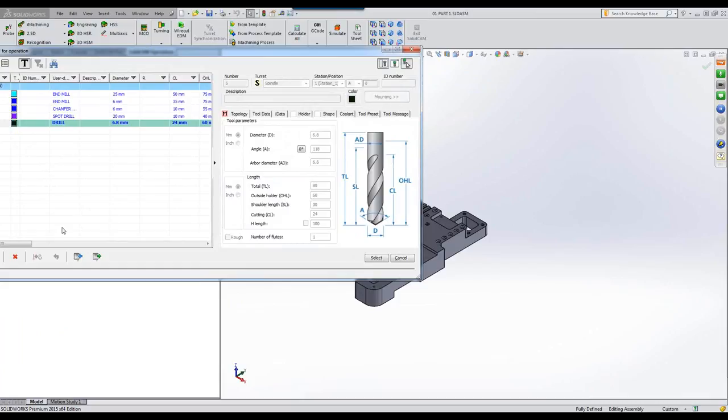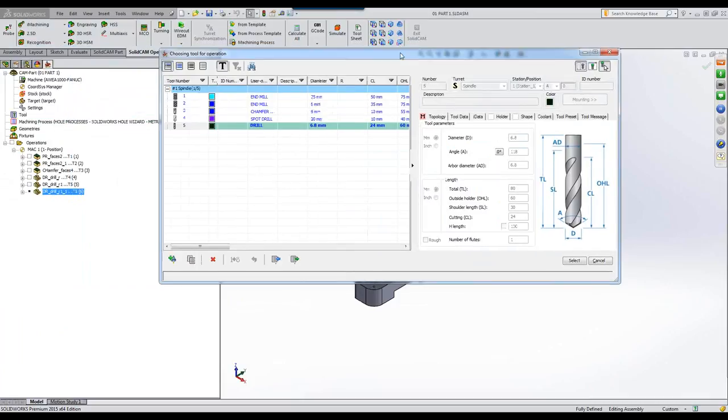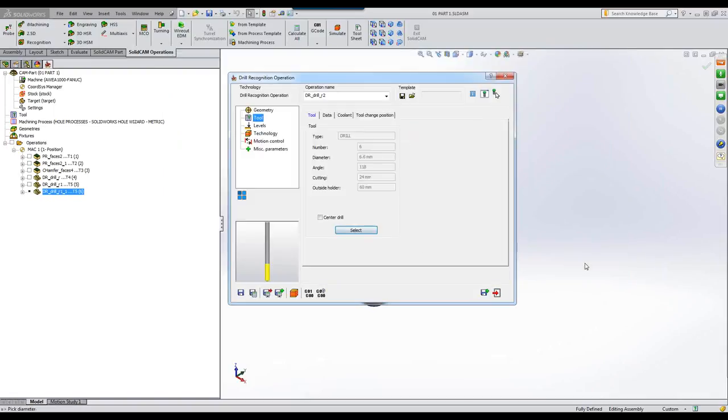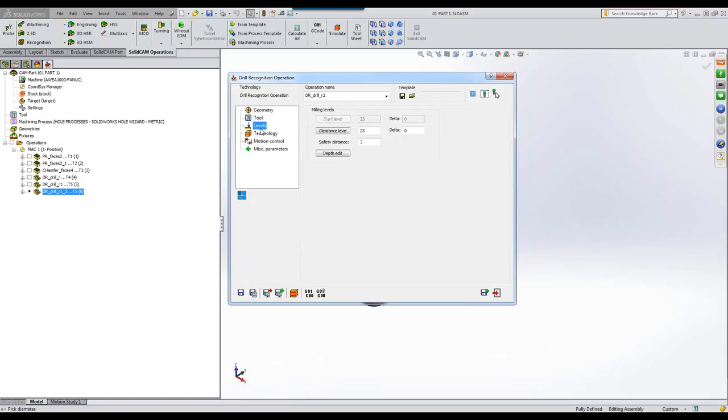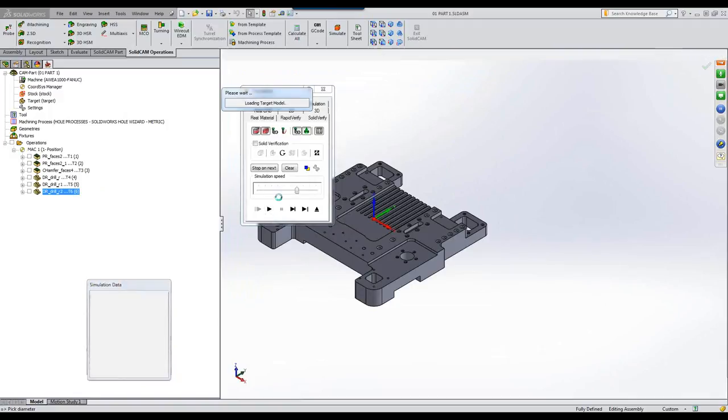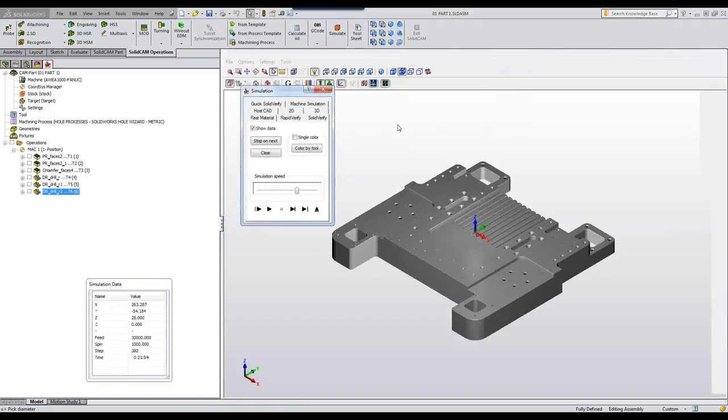I'm just going to copy the old one and just change the values. So I'll do copy, and the new tool will have 6.6 diameter drill. The rest, I'm just going to leave exactly the way it was. Save and calculate, run my simulation, and it'll work on those holes as well. And I can go on and on with this part.